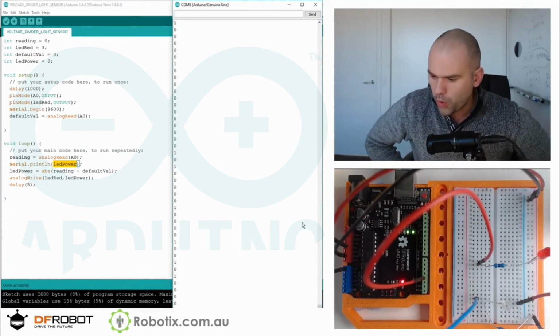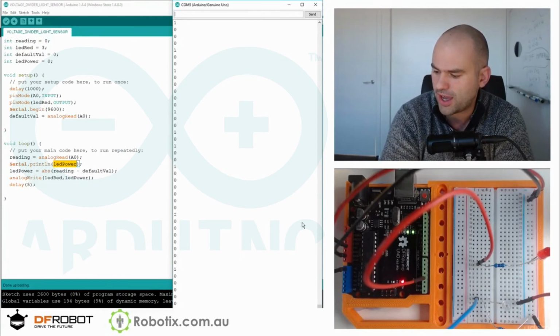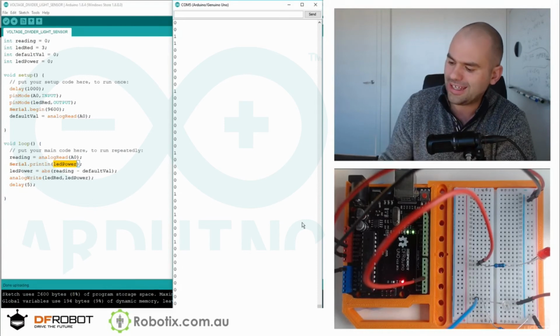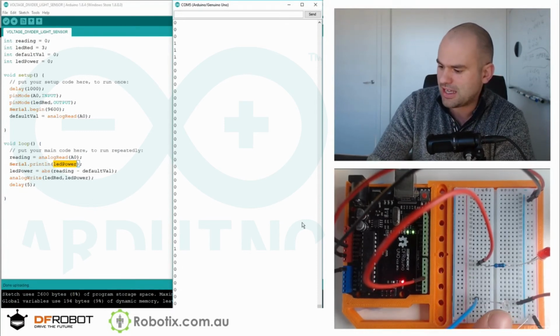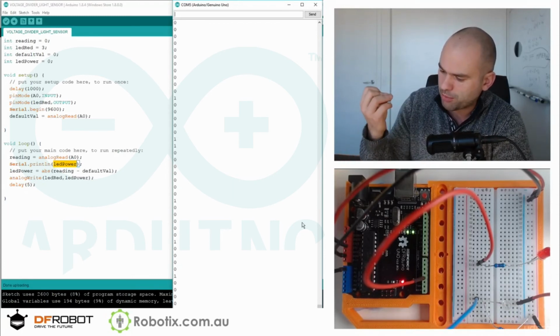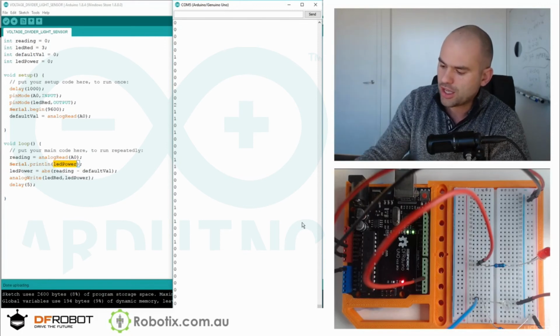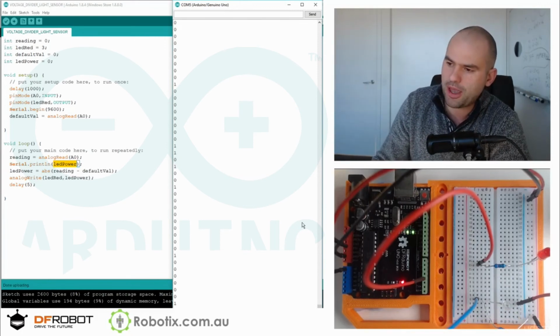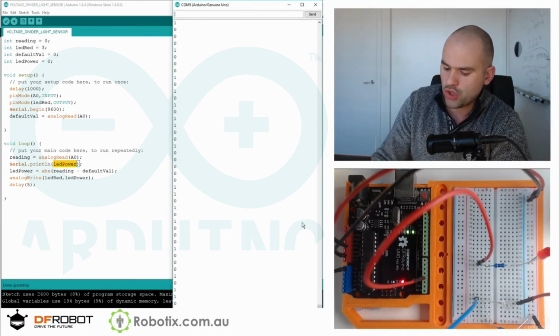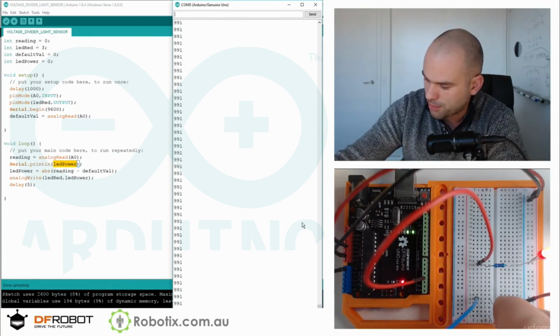So what you have here is a demonstration of how well voltage divider circuits work. All you need is something whose resistance changes in line with a variable that you want to measure. The resistance of this photodiode changes with the amount of light that is on it. You can change the photodiode to a light-dependent resistor. Straight up, completely different sensor, works on completely different principles.